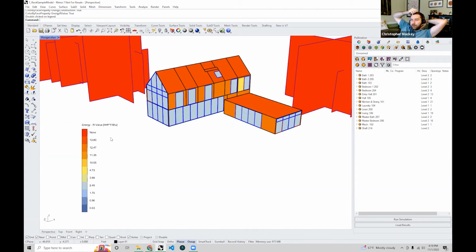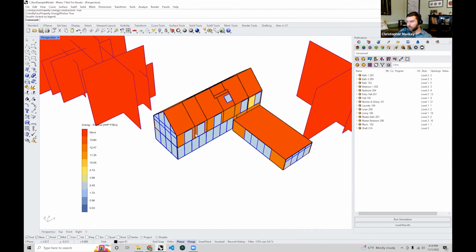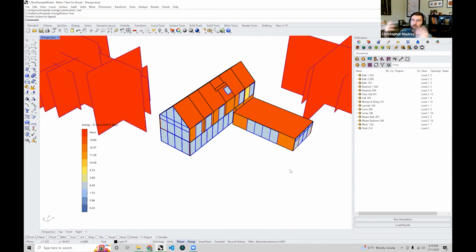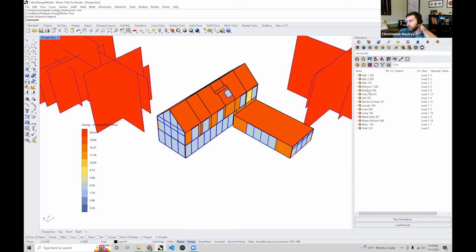I don't know if you're that familiar with the building code. Let's say this was in New York, using the latest version of the energy code. You may know that an R value of 13 is too low for a roof. This should actually be something different. This is a generic, typical construction, not really meant for a cool climate like New York. So let's say we want to set all the constructions of this model to be for the latest building code in New York.